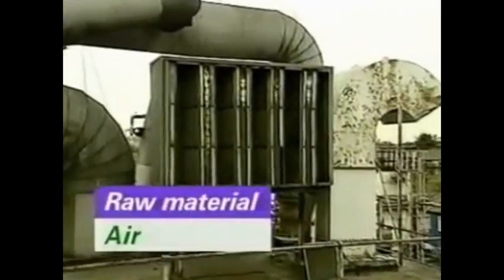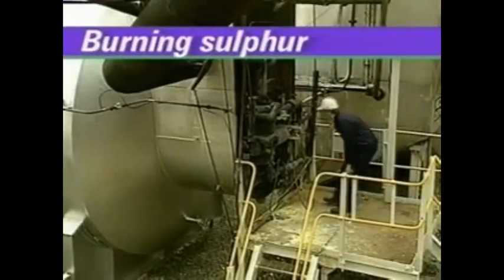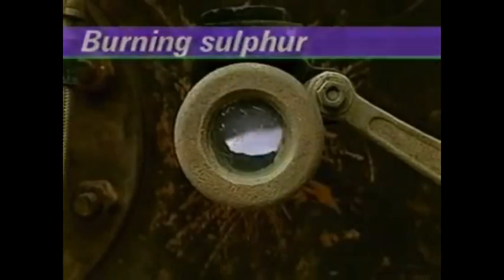Air, the second raw material, is drawn from the atmosphere, dried and compressed. The sulfur is sprayed into a furnace where it burns in the dry air.